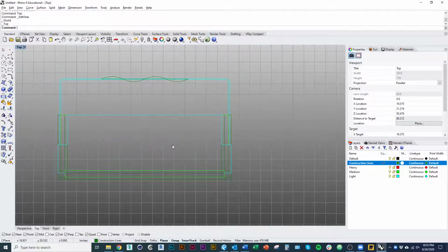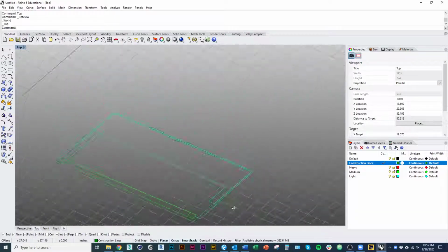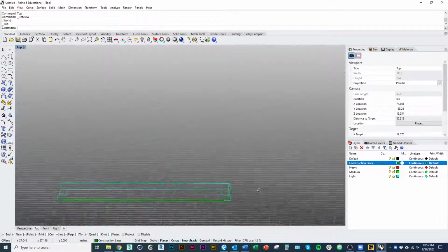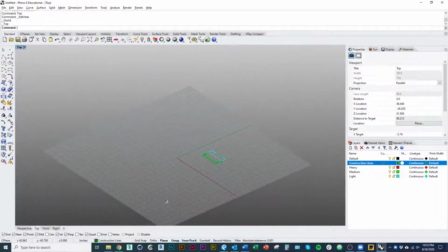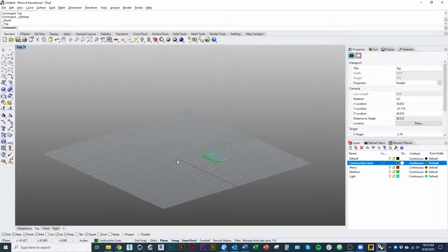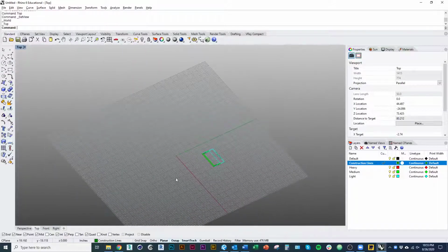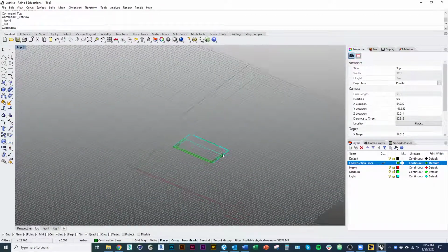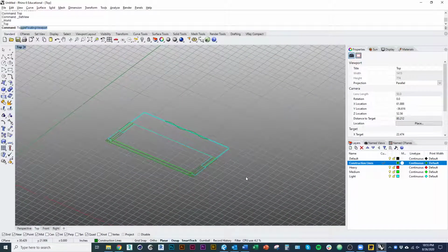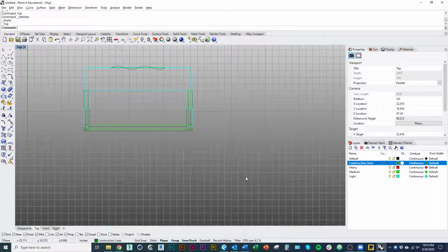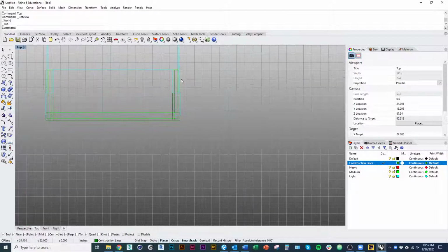You can also tilt and 3D orbit by holding Control and Shift, right-click, drag, and that'll allow me to orbit any viewport. So you can see, even though I'm in top view, my construction plane is still the XY plane, kind of looking in. That's something that you'll find when you start 3D. For now, I'm just going to make sure I stay in top view. I'll type top and press enter. Okay.